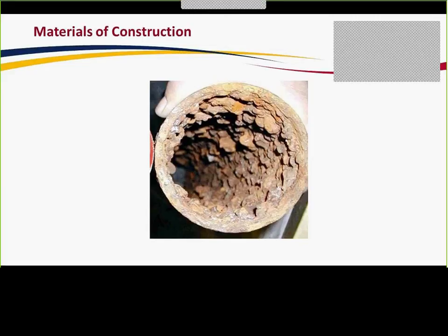A few select heat exchangers, specifically the tubes within the heat exchangers, were deemed necessary to be made out of austenitic stainless steel or duplex stainless steel to ensure that there was no erosion or corrosion caused by water, specifically utility water, above 50 degrees C, or high speeds caused by velocities of the liquids within these tubes.